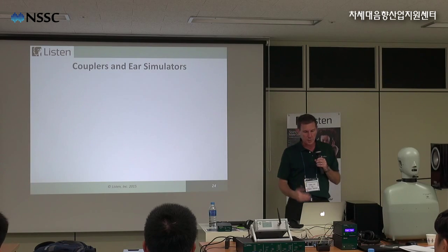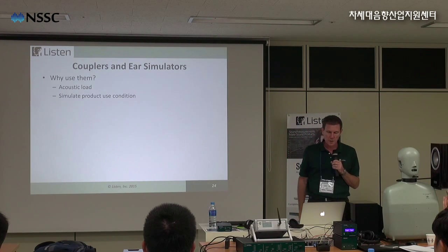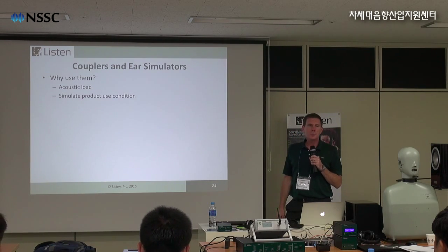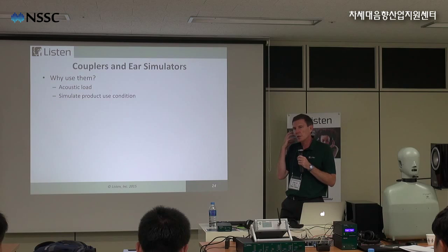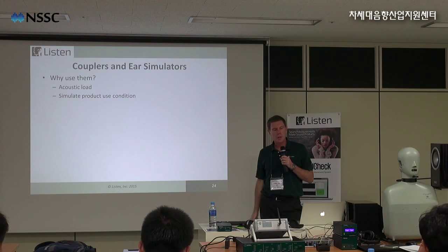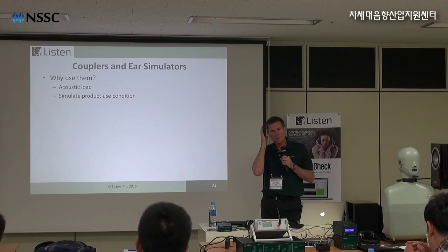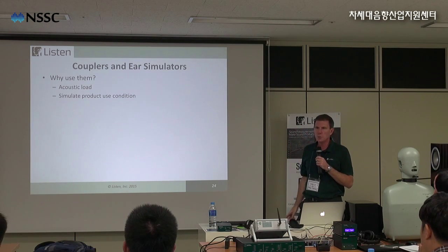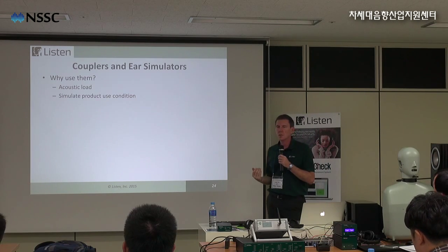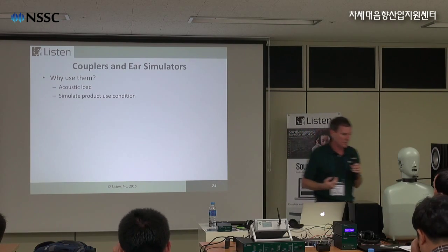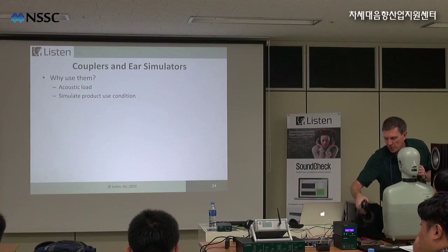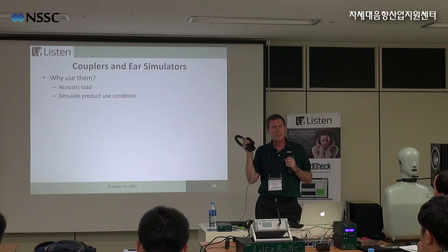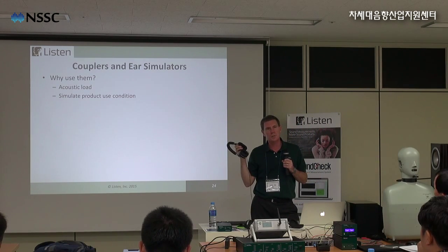So now let's talk about couplers and ear simulators. So why use them? So really the biggest reason to use them is we want to simulate the human ear. And the human ear is a mechanical device and it has an acoustic load. What do I mean by an acoustic load? Well, basically, probably the best example of this, if I don't hold this up against my ear, I actually don't hear very much sound coming out of the headphones, right?